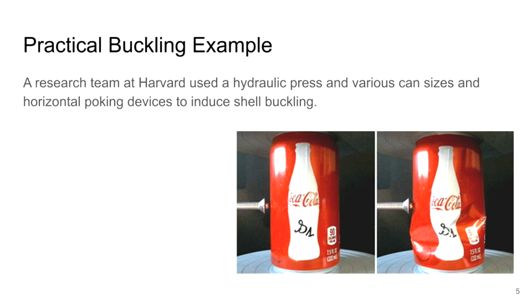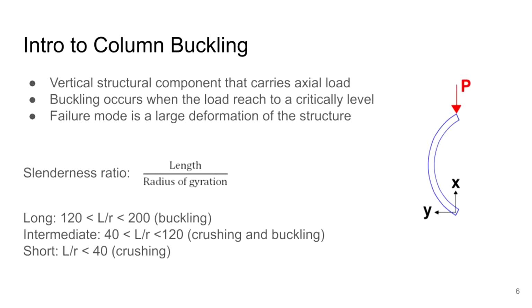But beyond a threshold axial load, all cans buckle once the dent is sufficiently deep. Because this sudden offset effect is indicative of a general behavior known as a nonlinear instability, the team suggests that all dented can-shaped objects have a similar stability landscape. If this universality holds, then other researchers might be able to use the stability maps for this Coke can to predict the strength of a space rocket or another similar object just by gauging its response to a gentle poke from the side. A column is a long structure of beams that carry axial load.